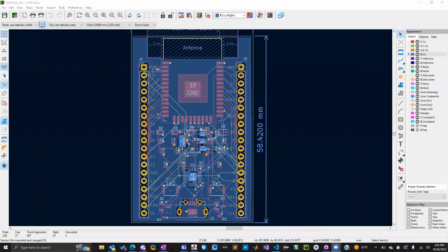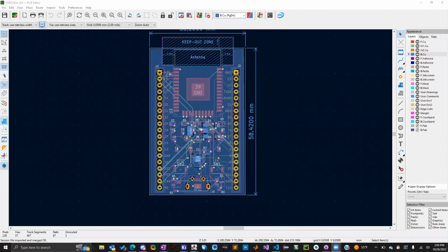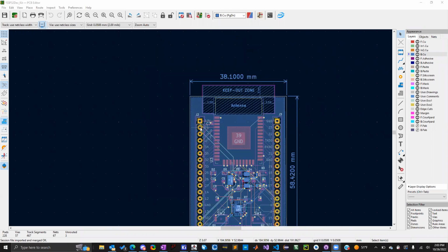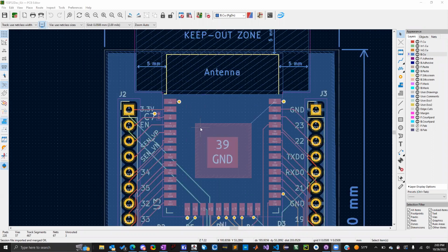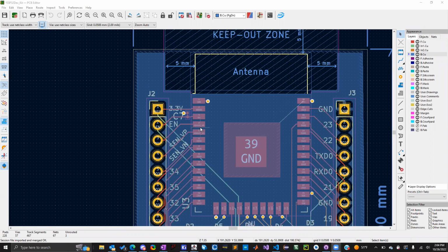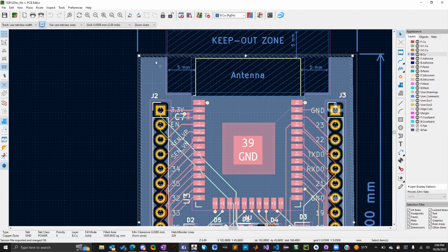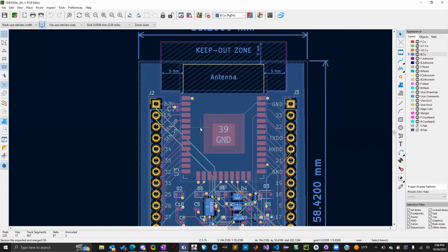Okay. So today I'm just gonna spend all this time talking about the auto router. Some things we discussed about the auto router is always do your grounds last because normally, and this isn't always the case, but normally you'll have a ground pad and you will be able to make much better connections to your ground pad than the auto router will.